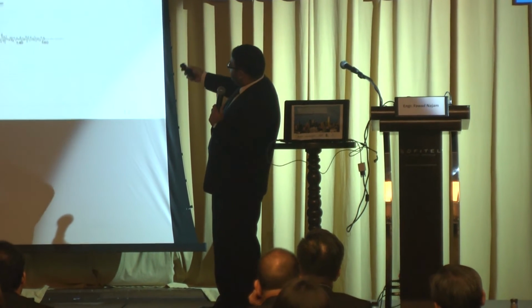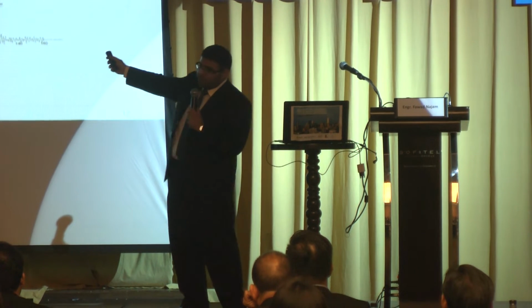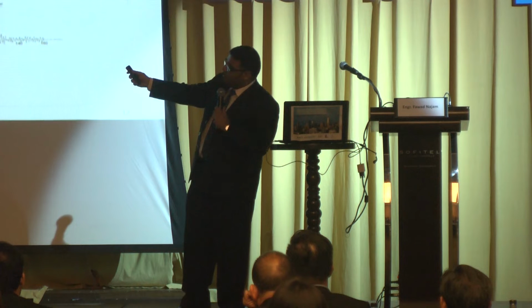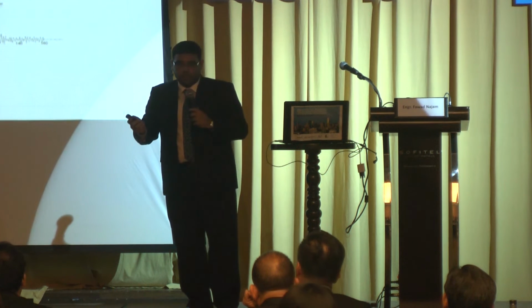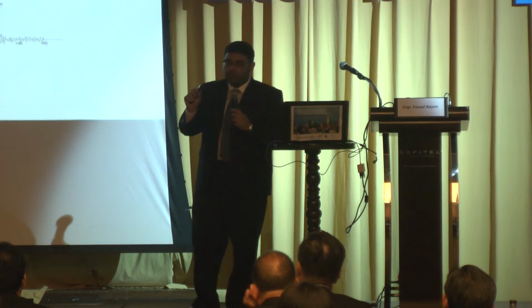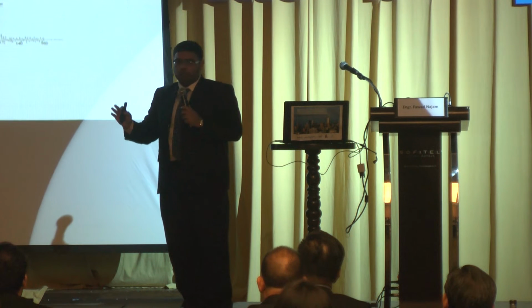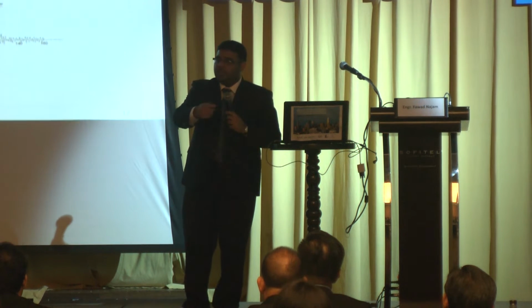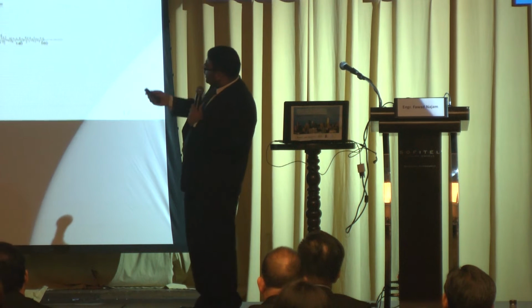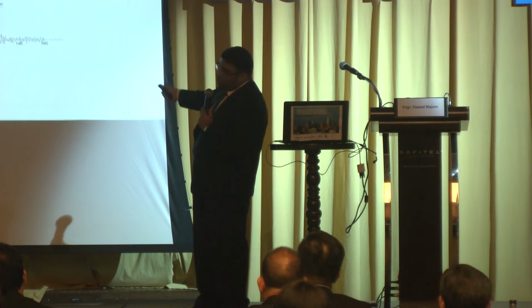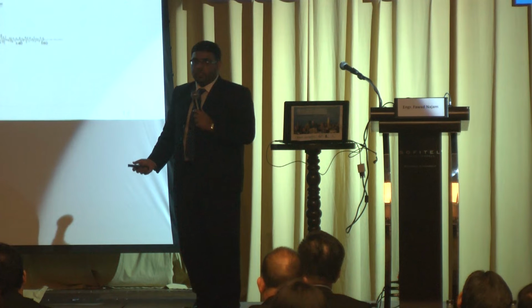If you have a lot of these single degree of freedom systems and you subject each of them to one ground motion and sum their response, it is expected to remain the same or equal approximately to the time history analysis of the actual multiple degree of freedom system. So this is the basic idea of modal separation: we convert each vibration mode of a multiple degree of freedom system to an equivalent single degree, we run the ground motion on that, and then we sum them to get the combined response. So the combined response of these lollipops should be equal to the time history results of this multiple degree of freedom system.